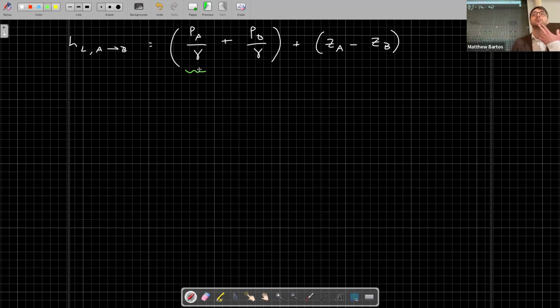Okay, we know from the problem statement that the pressure head at the upstream end was how many meters? 8.3. At the downstream end, it was 76.7. What about ZA minus ZB? Okay, we know that the elevation difference is 100. So ZA minus ZB is 100. And we can explicitly compute the head loss knowing these facts. So the head loss is known and it's equal to 31.6 meters. Okay, so we can know the head loss just by taking pressure and elevation measurements.